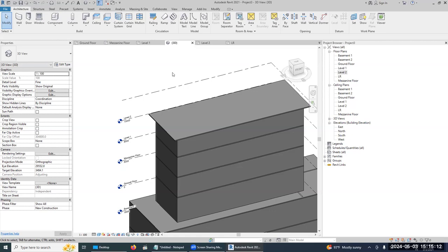Okay, now you have to do the roof. Go to level 2 and again take floor, but this time you will say roof. Now take rectangle. When you click it here, it automatically gives a 900 offset. And say finish, attach. And when you see the 2D view, it's again.